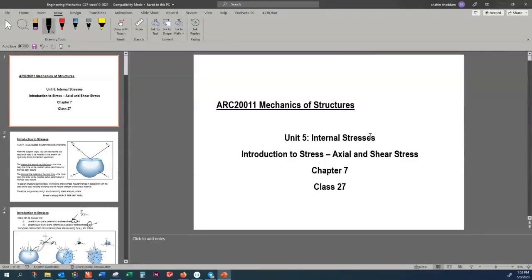So today we discussed the average stresses, whether they are due to shear or tension inside the two-force member, or in the case of bending, we introduced the flexural formula. The flexural formula tells you how the normal stress in a beam due to bending changes in the y direction. And we solved a number of examples for that, and that brings our lecture today to an end.